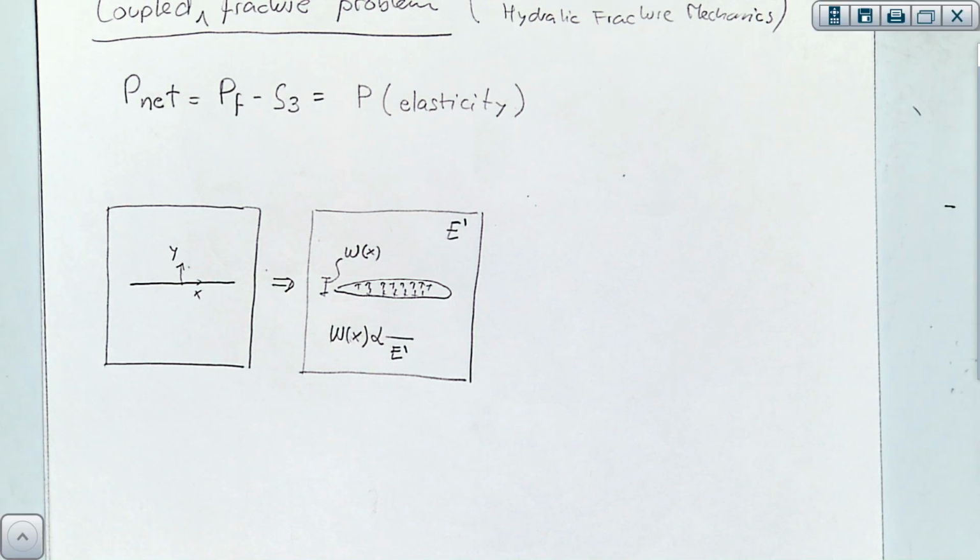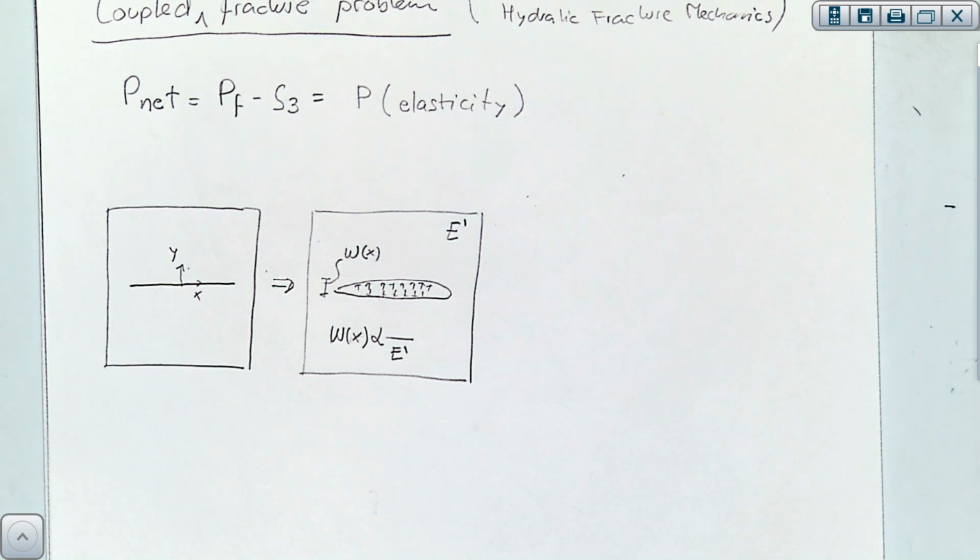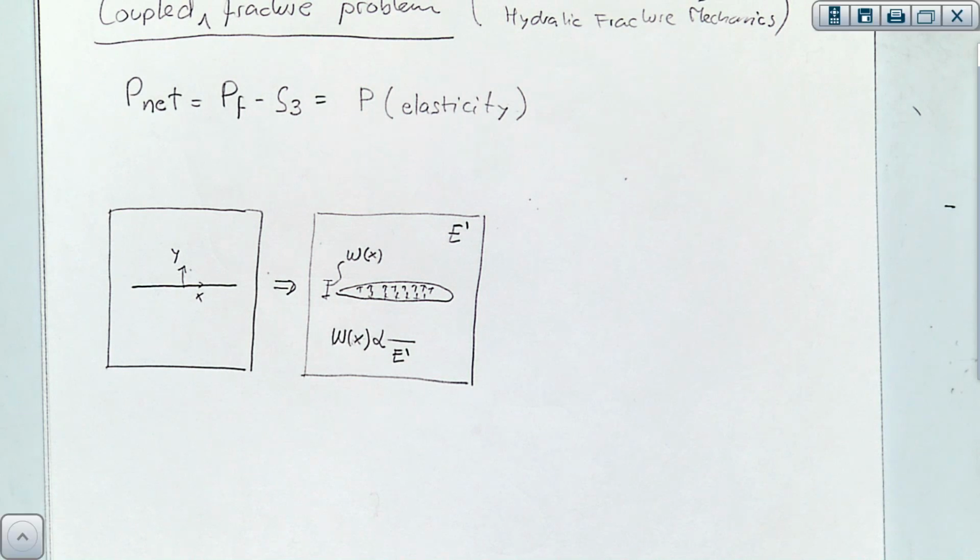This part, in order to solve this, what you will have to do is exactly what you did in project number 6 or method. You found what will be the pressure needed to open a planar fracture. If you set the pressure, right? Yeah, now I remember. So you set the pressure, and then you get the displacement. Displacement is basically the fracture aperture. So the higher the pressure, the higher the displacement; the stiffer the rock, the lower the displacement.